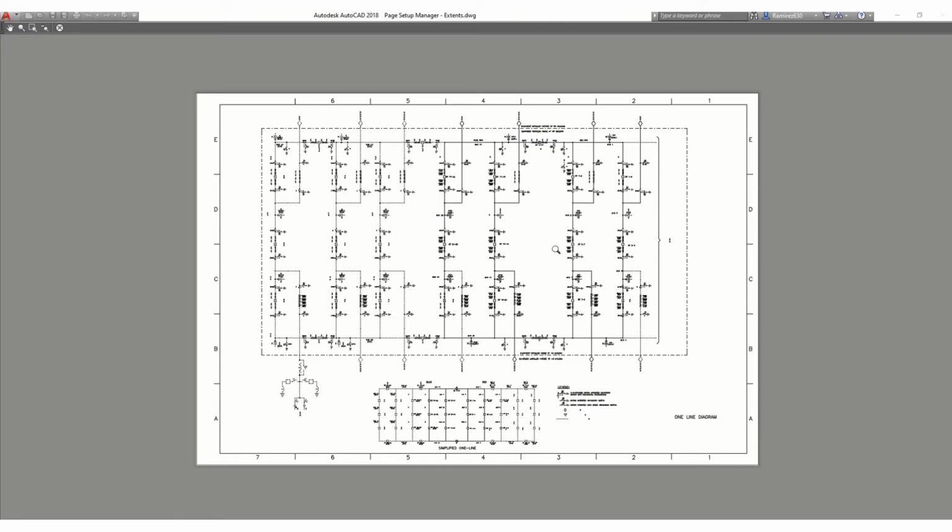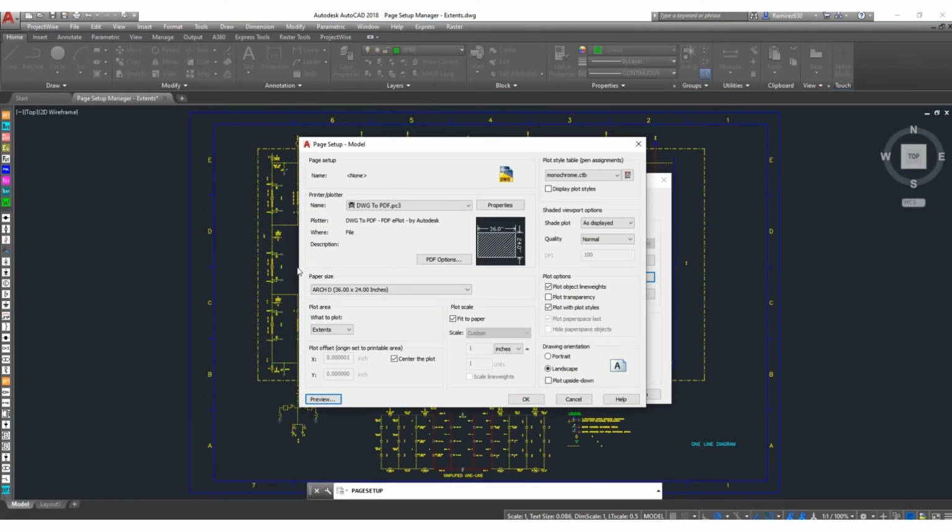All the settings for this video pertain to this setting. Once you're done, actually, sorry, one more thing. Make sure your plot style is set up. I chose monochrome as display normal. Try to make sure you have these two checked in there, because with plot styles, it's going to give you a faded look on your border.